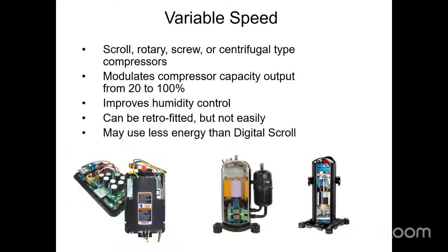You can also put an inverter on the compressor. This is becoming more and more common, and it is for all types of compressors at this point. Obviously, you can get scroll inverters, even residentially. I mean, I've had a scroll inverter at my house since 2015. Actually, I don't have that. I have a rotary compressor with an inverter at my house since 2015, and it's one of the ways to get really good dehumidification.